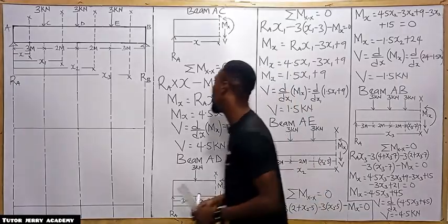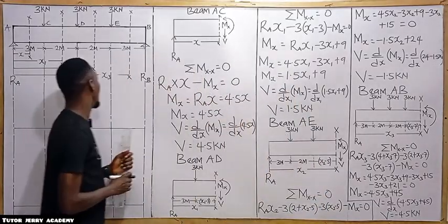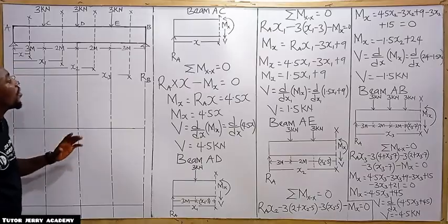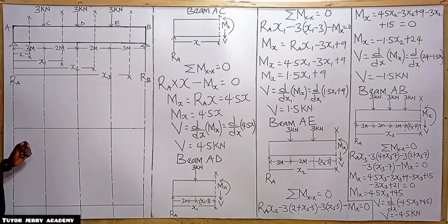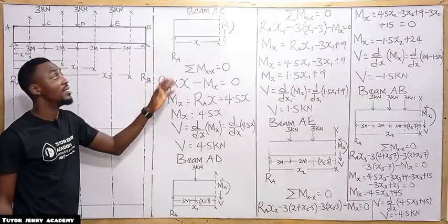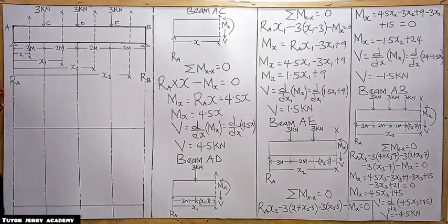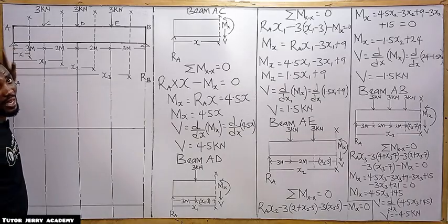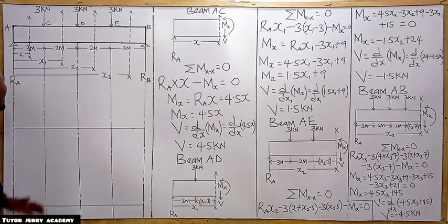All right. So now, let's get into work. So for us to start with the shear force, we start the sectioning of our beam from the left hand side to the what? To the right. So it shows that our shear force diagram will also start from this left hand side. And for us to draw our shear force, we are going to consider beam AC first.